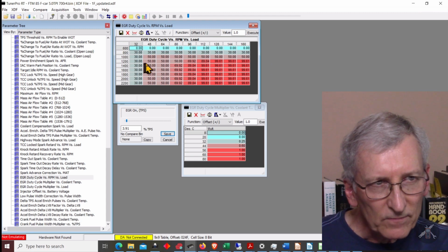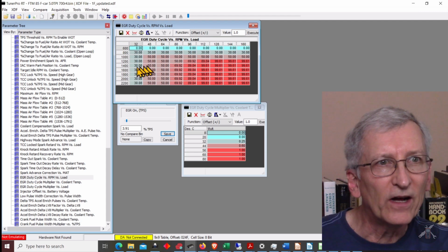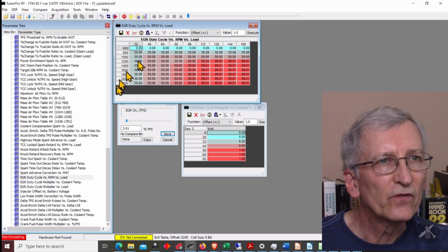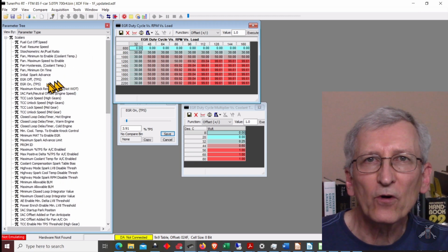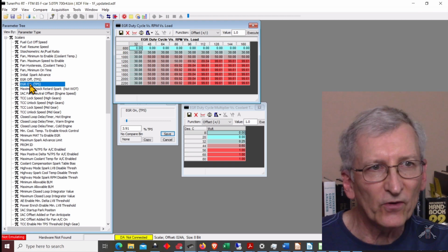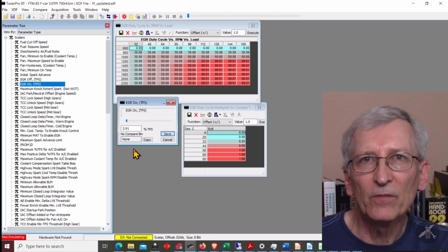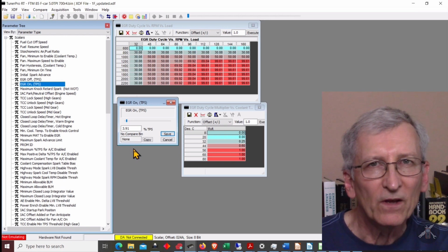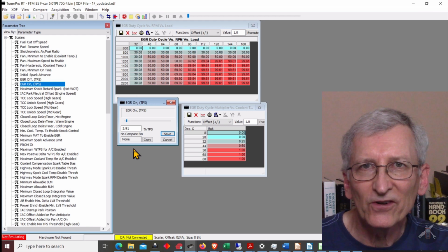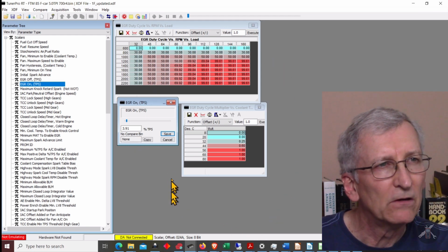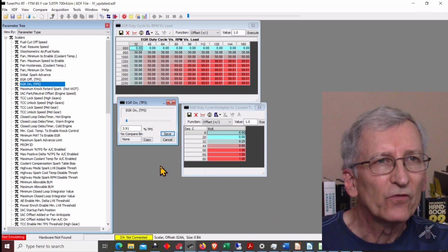Well, on mine, again, I'll go back to 85. If I go up to the scalars, this is where I picked this one up. So EGR on is right there. It's at 3.91, so 4% throttle. So it doesn't take much throttle as you just barely crack into the throttle. And once you get above 800 RPM, EGR is going to start coming on, as long as the negative back pressure doesn't turn it off, right? Interesting stuff. So that's my 85.